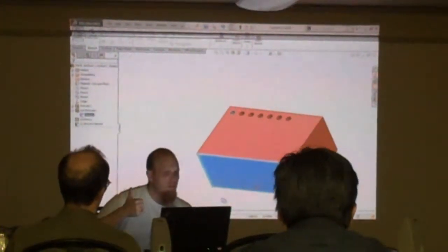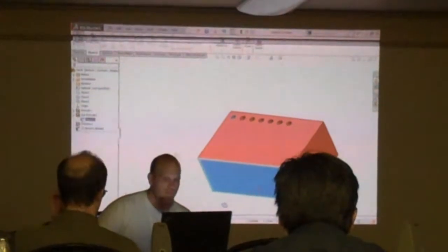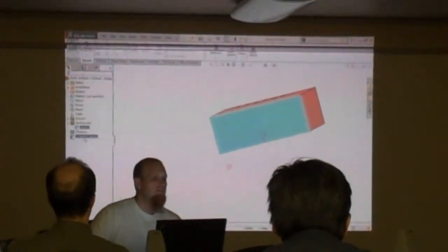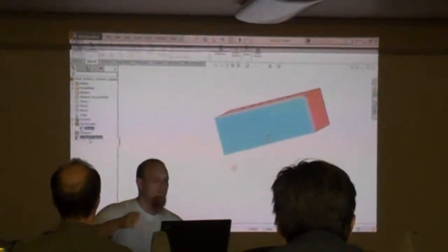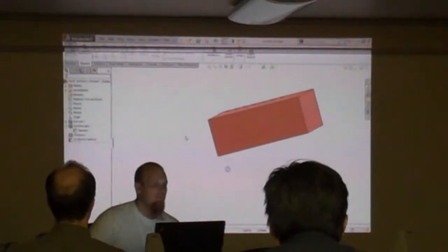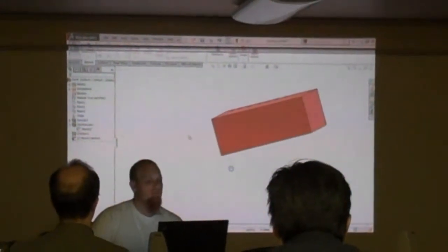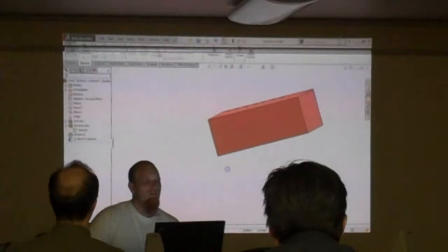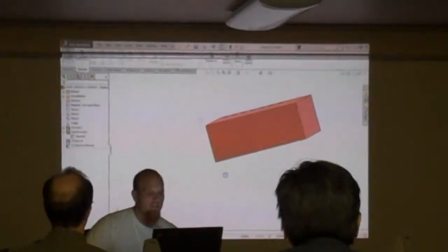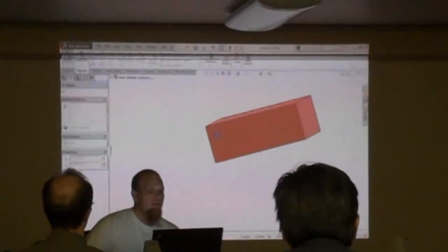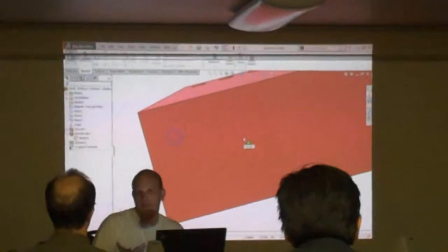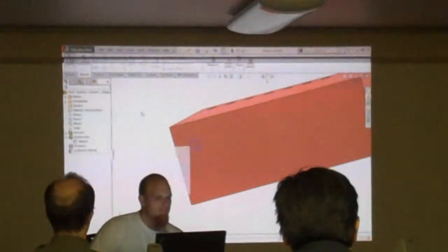It clones, not copies, clones the particular sketch, and creates a sketch, in this case sketch 3, takes the next number, and adds derived at the end of it. What does the derived mean? For one, I'm in a sketch, I got sketch geometry on the screen, but there are no sketch tools available. There's no lines, arcs, fillets, offsets, or anything. All it cares about is its XY position, basically. How are you going to constrain this guy to be wherever it needs to be in the design?